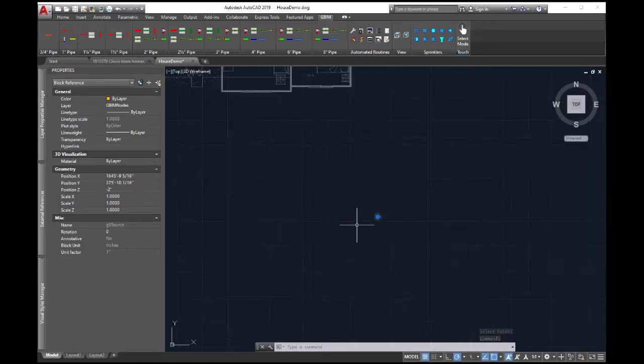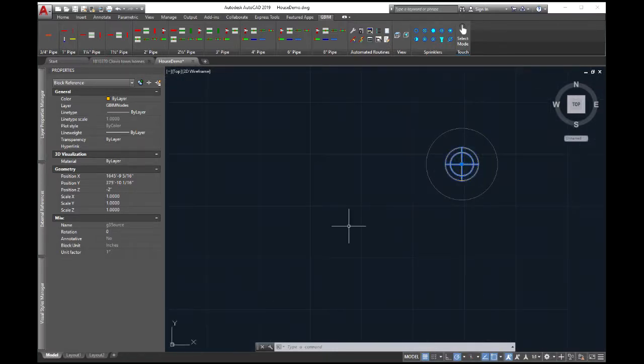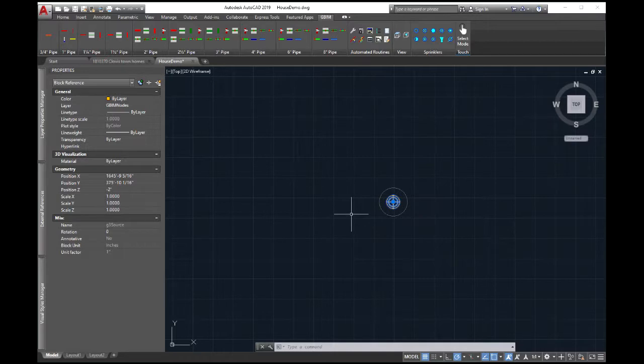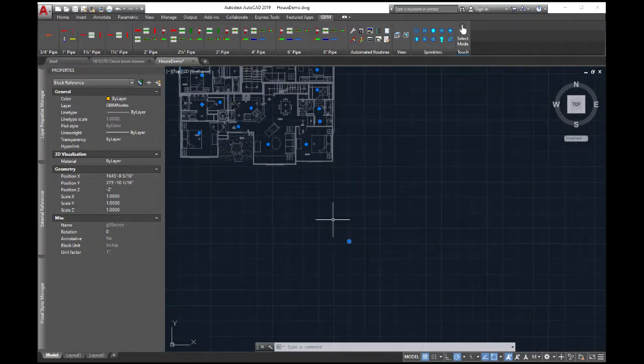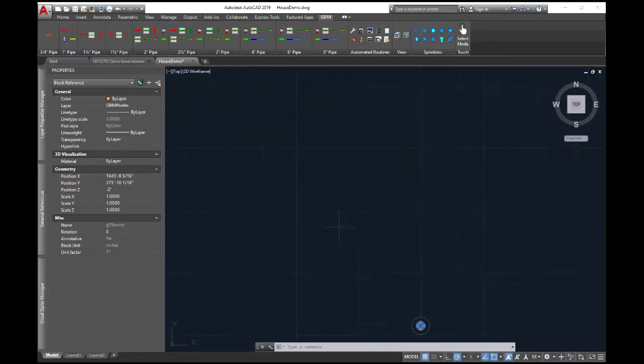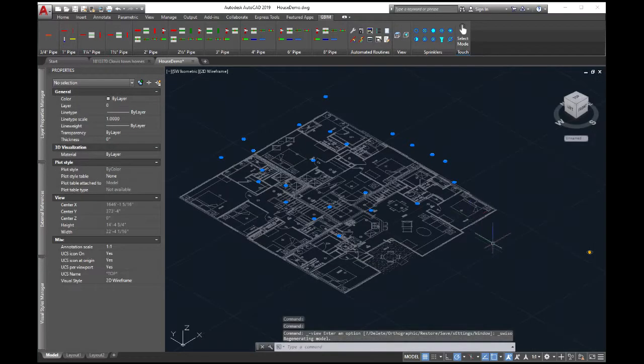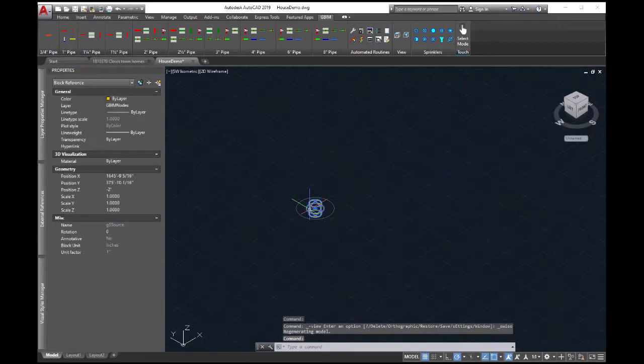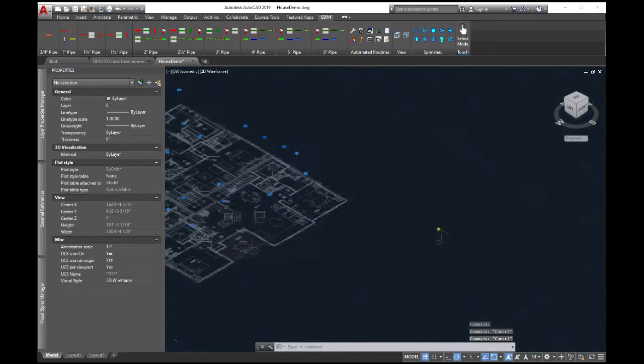Right now it's at a -2 height. There's different ways of doing this. The pressure reading was probably taken at about 2 feet above, so you can get a couple of pounds that way. Oftentimes I will elevate this to maybe 2 feet above, and so now we can pipe in our underground.